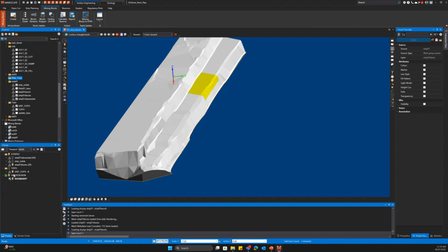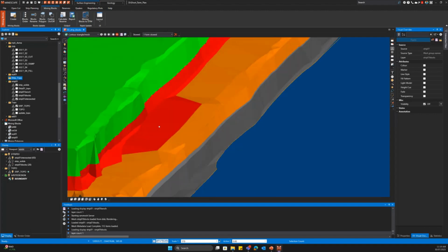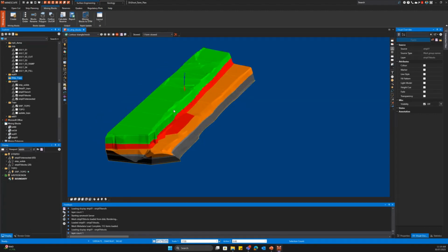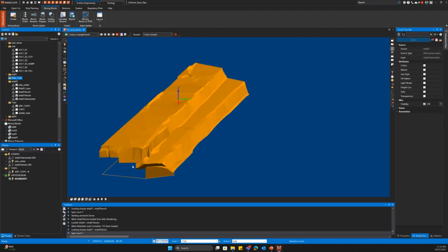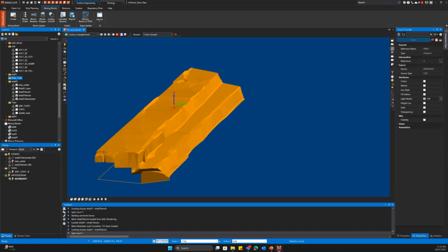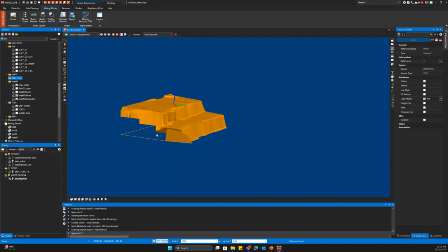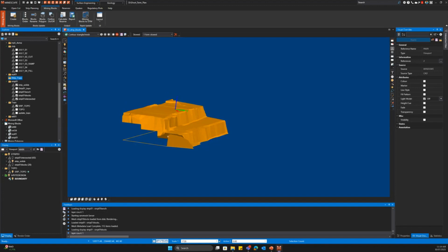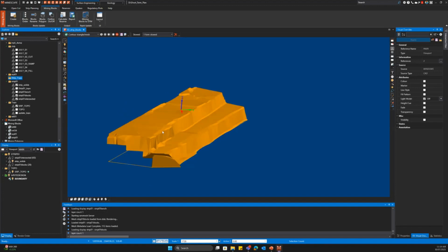You can see this. So I'll show you this now, where it's intersecting our different intervals. So we know this is the top surface, or the overburden, then the second overburden, then bench 2, bench 3, until we access our coal. And it does this so perfectly that it follows through with the different angles that you have defined. So we create all these surfaces like this. If you have different angles, it will follow through like that.